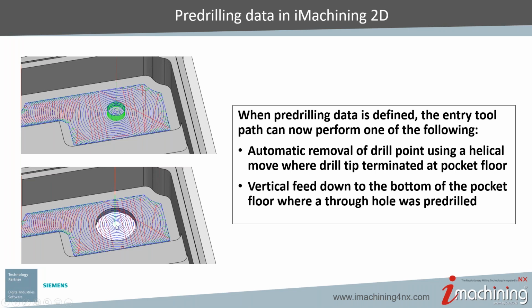If we look down here at this pocket, if you're machining a through pocket and your drill is able to go all the way through, then there's no tip to clean out. This is a really important thing because in the end, helical entering is definitely one of the most challenging things for end mills. And I would say with a lot of the specialized tools coming from manufacturers for radial engagement tool paths, a lot of these tools don't really have the ability to do center cutting.